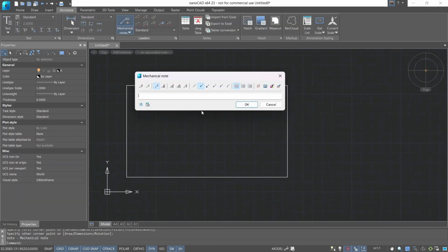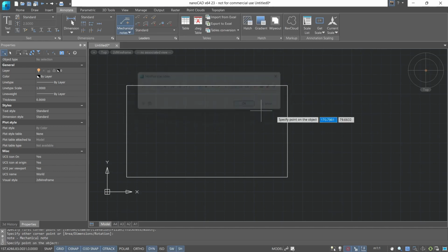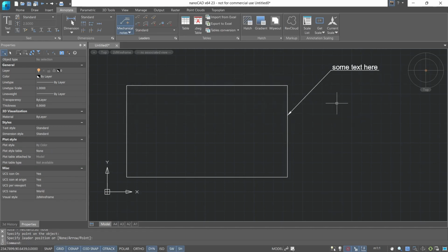Call the universal note, after which the following dialog box with function settings will open. Settings like Add String, Remove String, Simple Note or Multiline Note, Frame, Types, Arrow Formatting, Text alignment, and additional tools, for example, Insert Special Symbol, Notebook, Match Properties, and Add Extension Line. Let's write the text in the field. Then we'll specify a point for insertion on the object and continue editing.